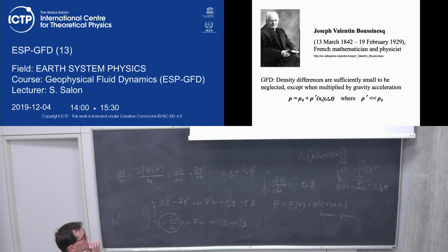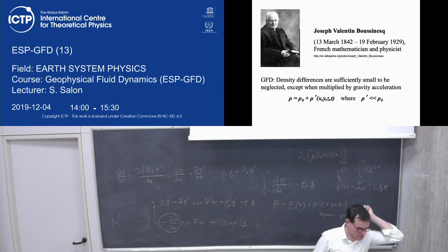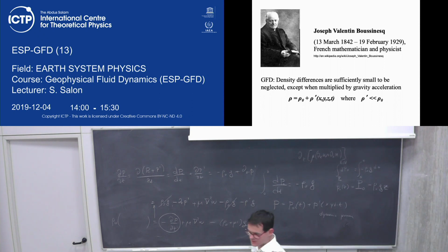So we have also the third equation. We did the mass equation converted to a divergence-free form. We had a simplification of the stress term, and we obtained only the Laplacian in the horizontal components. Then we also have an argument relating to the hydrostatic pressure, and we found the buoyancy term in the vertical component of the momentum. Now we need also to deal with the energy equation.